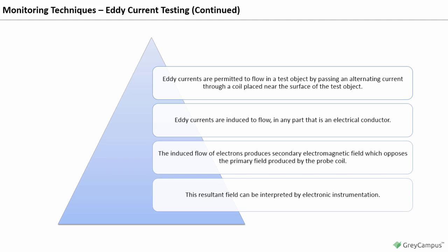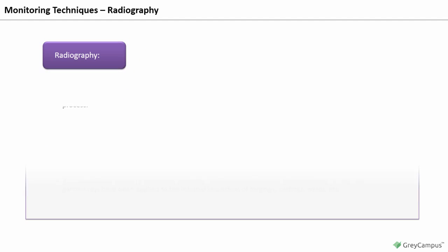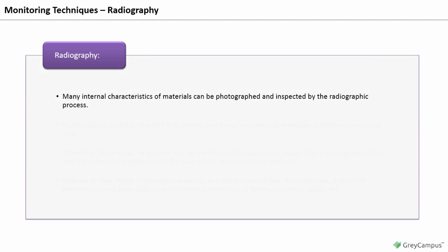Defect size and location cannot be read directly during eddy current testing. This test requires a comparative analysis. Part geometry may be a limitation in some test applications and a benefit in others. Eddy current methods can be used to check material thickness, alloy composition, the depth of surface treatments, conductivity, and other properties.